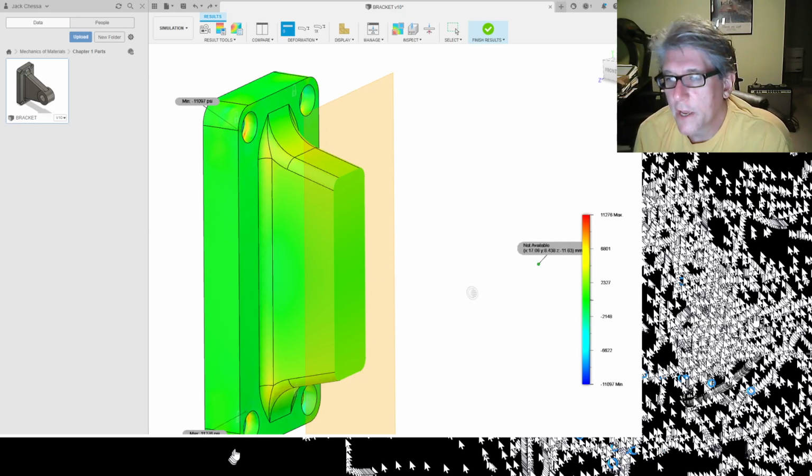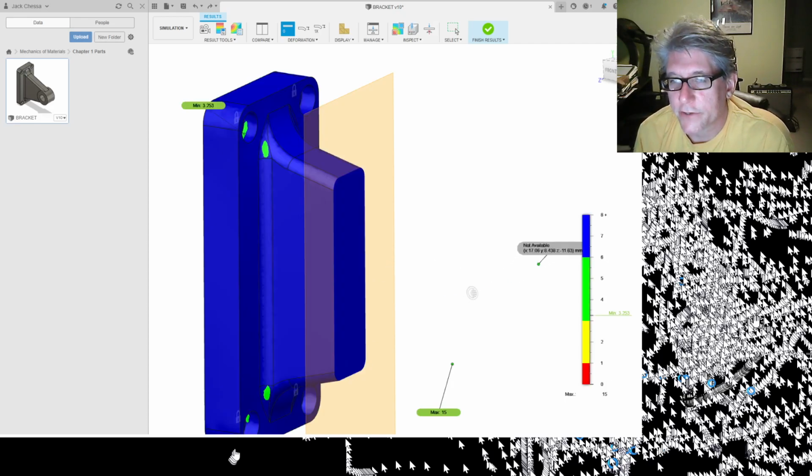force over areas. If you want to actually look at the factor of safety here, you can just change the display from stress to factor of safety. And then again, you can drag the probe over the surface, and you can see it's pretty high here. It's staying at 15 the whole way, okay? You can see if we go over these higher spots, the factor of safety drops down. So, all right. So I think that's good.